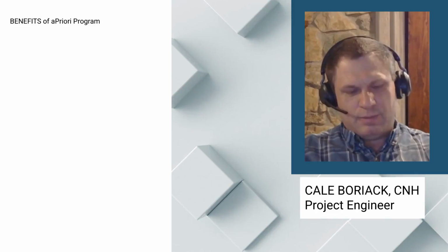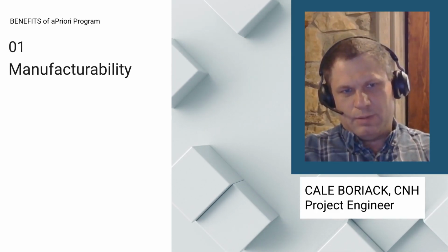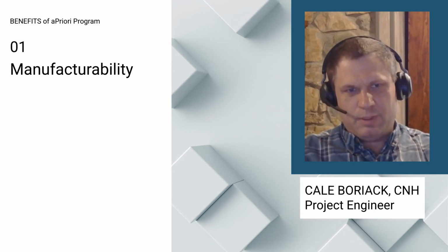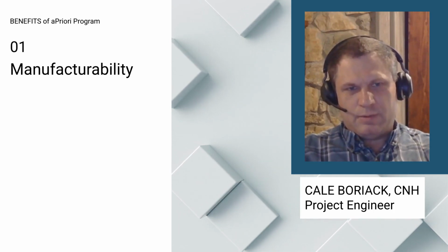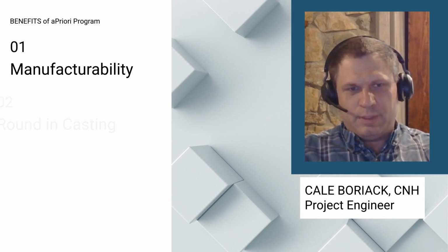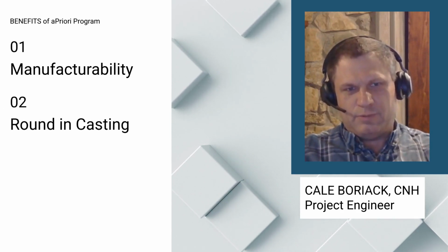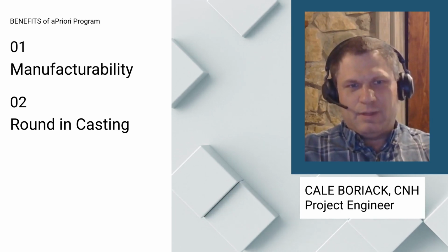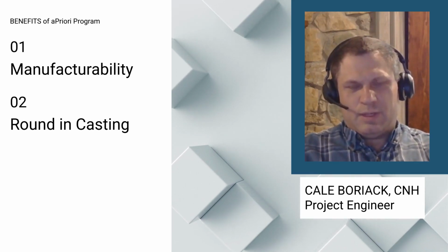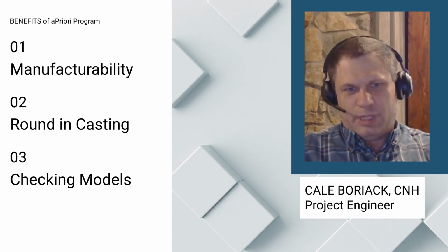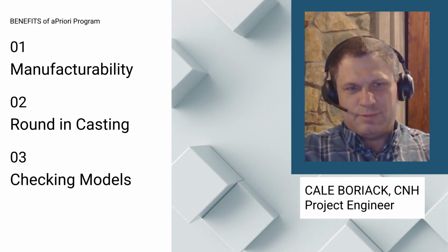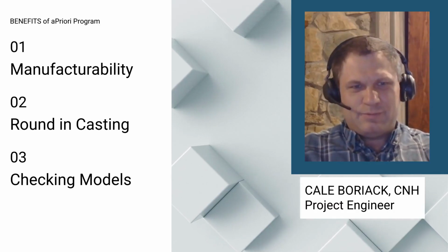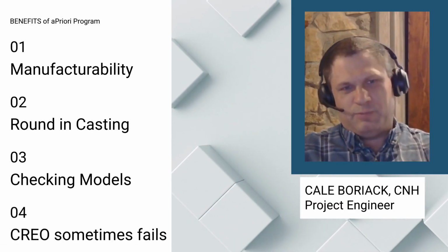One of the best things that I found with aPriori is the manufacturability aspect of aPriori. So if I've got a part where I didn't put a round in, for instance, in a casting, it's going to highlight that. And so I use it a lot of times even for checking my models to make sure that I've got the models right. Because what I've found is Creo sometimes fails on a round.